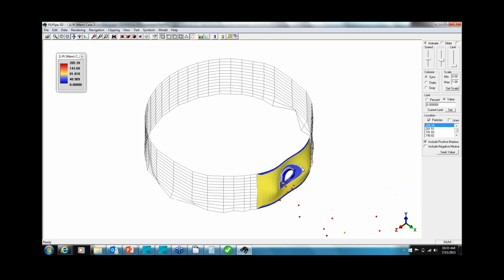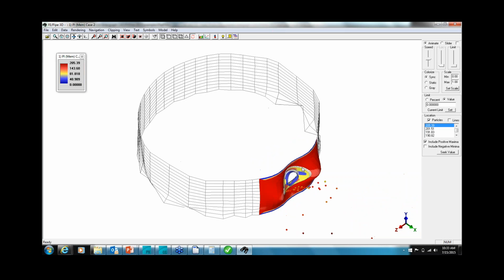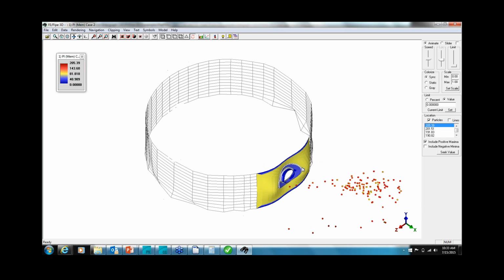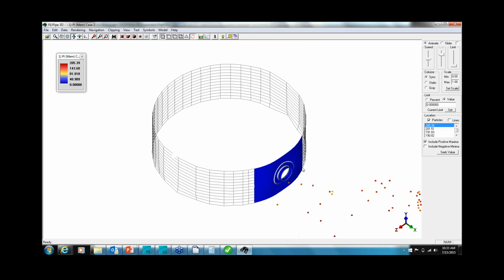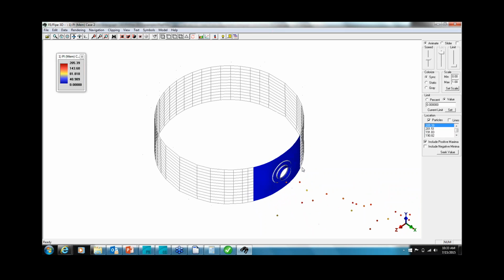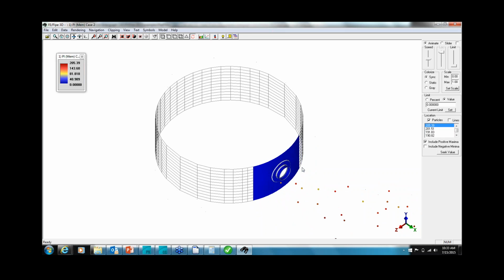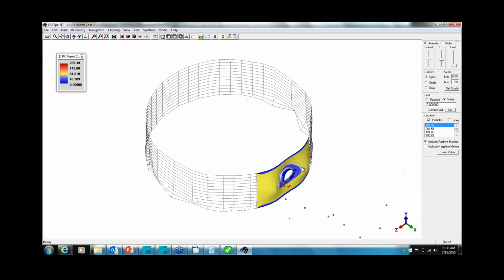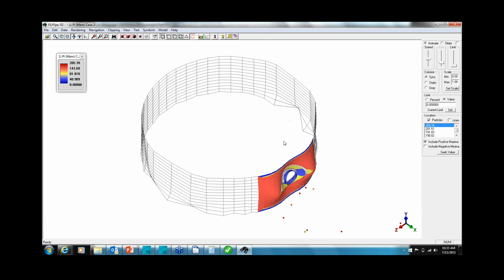Whereas when you perform the FE analysis, it is going to calculate the appropriate SIF values and reproduce the results with respect to this, compare with the ASME, and it will give you the actual results. So that's a place where you are trying to improve your analysis. Sometimes it is definitely going to help to save thickness of your nozzles or the reinforcement pad. So that's a place where it's going to add value to you.